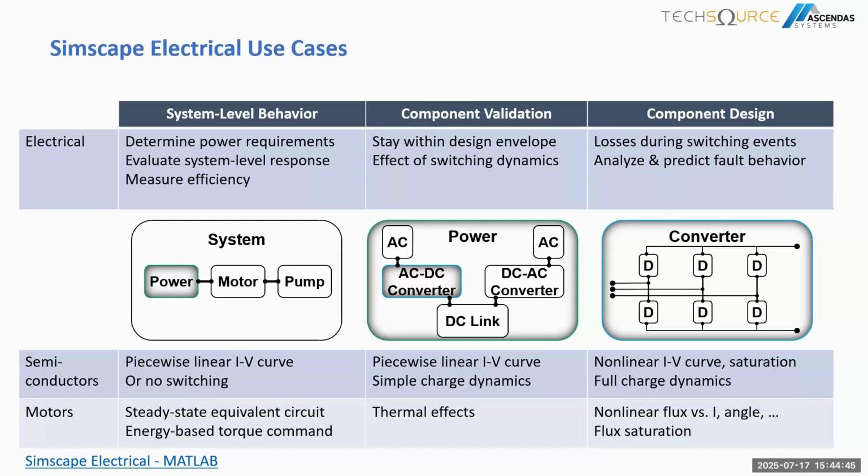So you are able to actually, for example, calculate losses during switching events, or analyze or predict fault behaviors. So in Simscape, you are able to provide some kind of fault analysis for your simulations and see how your system behaves. That removes the dangerous testing, for example, in actual physical systems. Instead, it provides a test for you to be able to do it in a virtual environment.